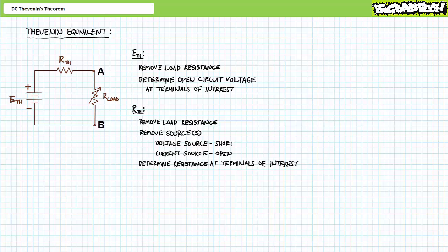The two steps in Thevenin's theorem make use of a shift in perspective from the source to the load. Thus far, we've been performing circuit analysis as if the source is the one that's controlling the show. However, the source is really only part of the picture. Ohm's law supports this duality. Voltage influences current directly. Increase the voltage and current increases. Decrease the voltage and current decreases.